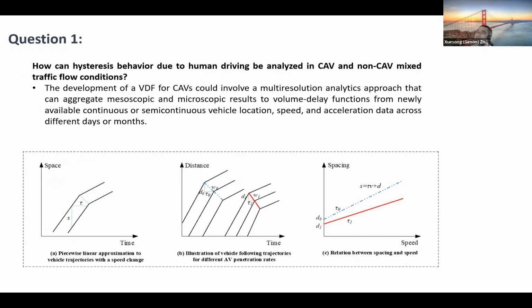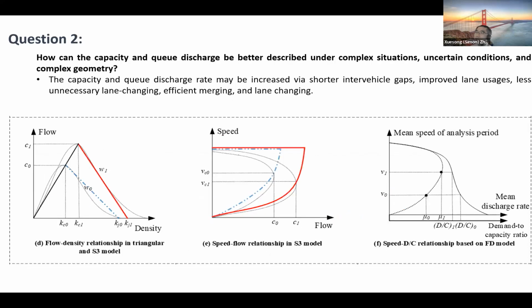I have a few more questions here. How we can understand these human-driven behavior model? So typically, within this car-following framework, reaction time tau, and the minimal spacing, human-driven versus CAV with a reduced congestion, reaction time tau, and the minimal spacing. So if we can understand all this connection, we should be able to answer question number 2, to link the corresponding capacity more realistically, and then to map the congestion duration, and then to map the jam density more precisely.